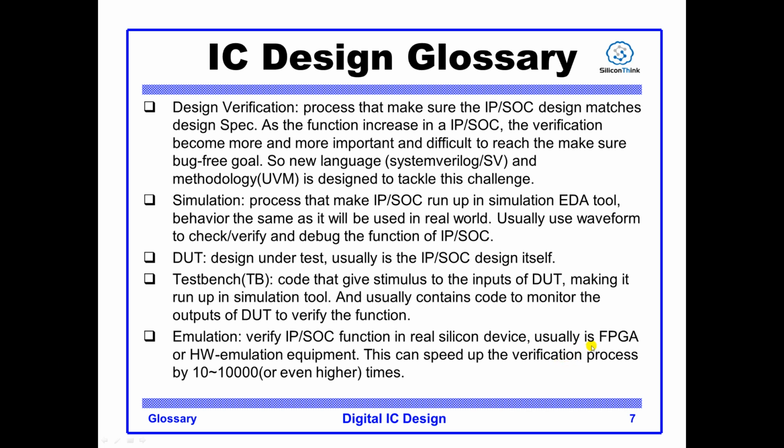So usually, if the design you are doing is not big, you can use an FPGA platform to do the emulation. But if you are doing some big design, such as the CPU core of your PC, you may use hardware emulation equipment to speed up the verification process.